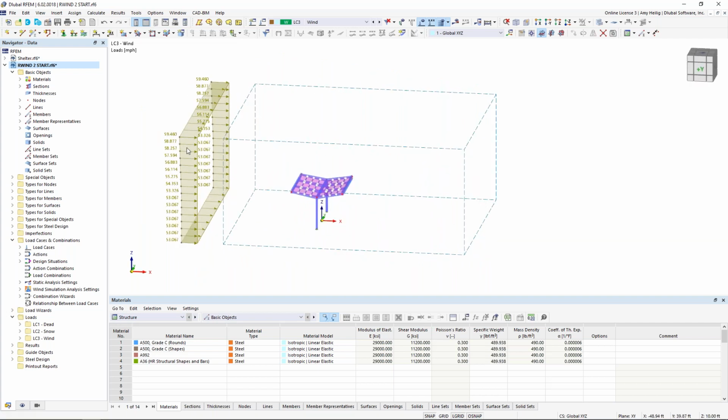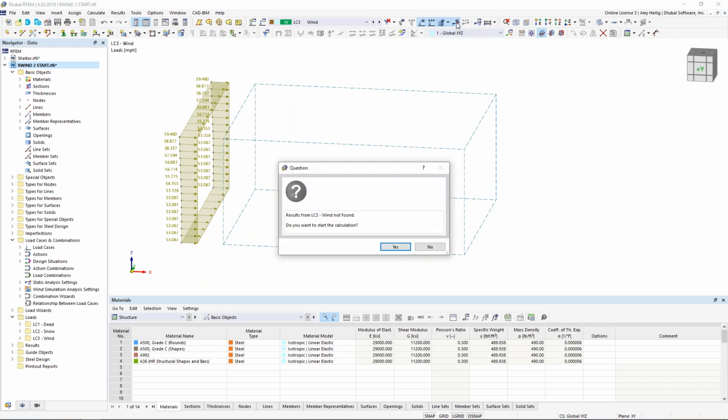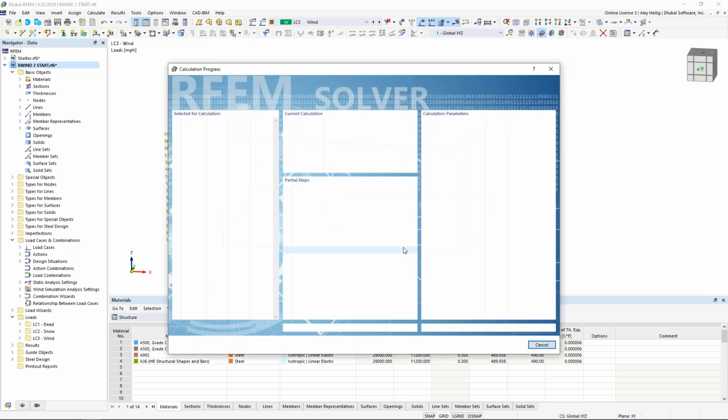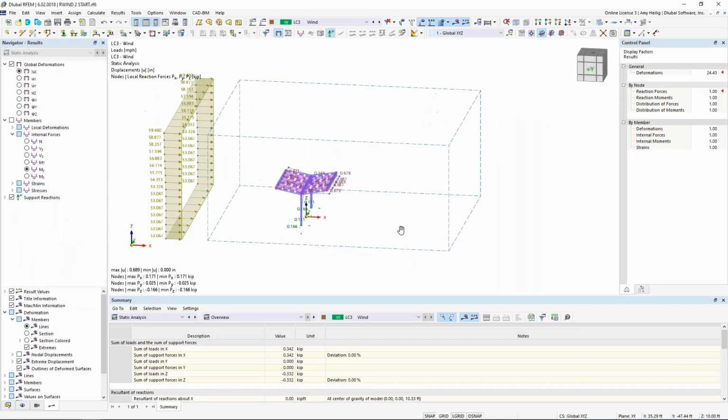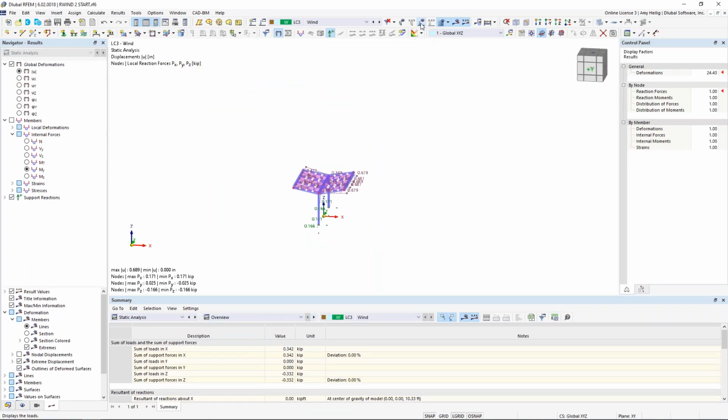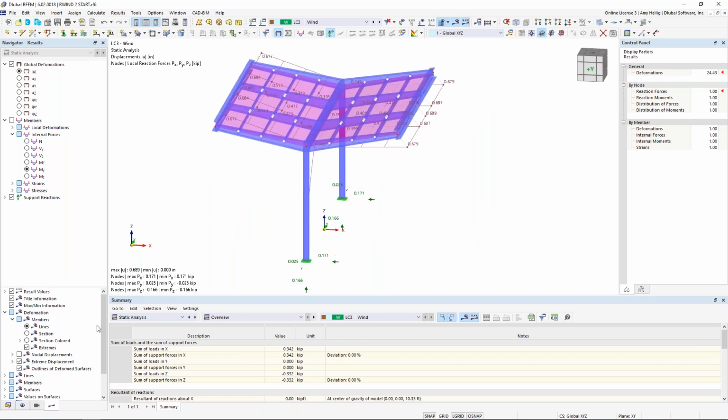And now that I brought the wind pressures, we've converted them to loads within RFEM itself, we actually have to run the calculation here for the true static analysis. So we'll go ahead and start this calculation. Once that's complete, we can deactivate the view of the loads here and zoom in. We now have an available tab to us in the project navigator for our results.